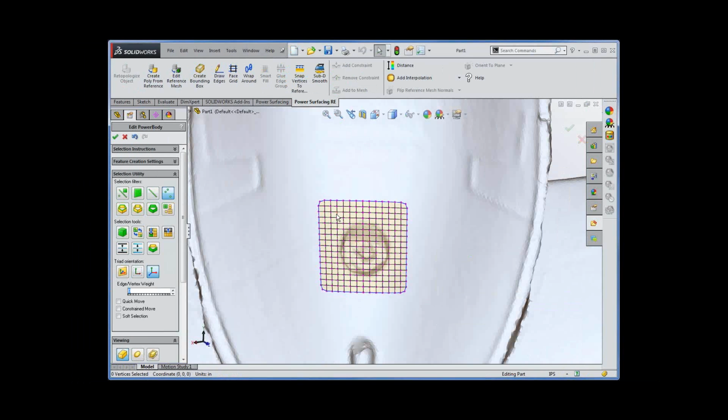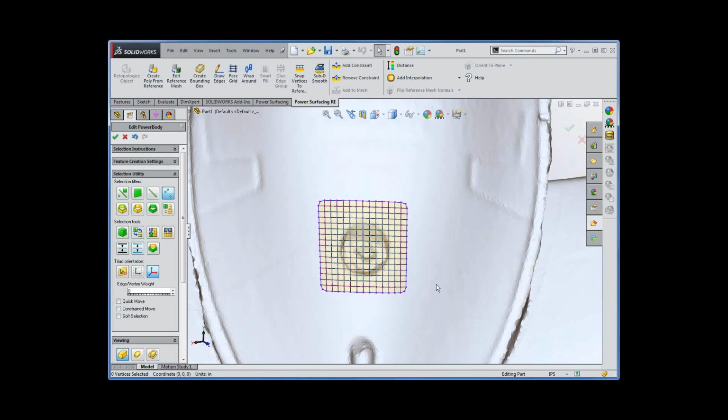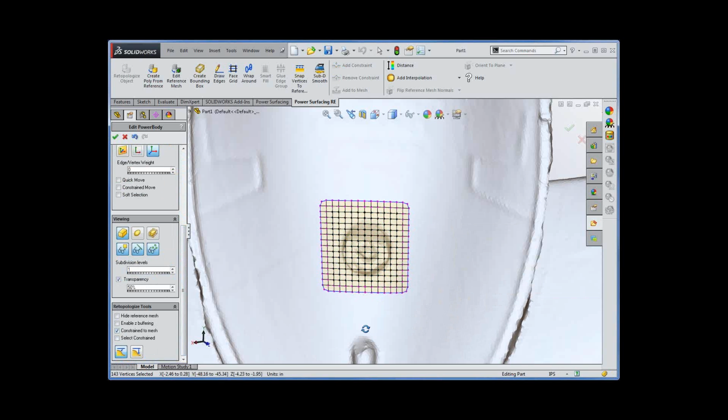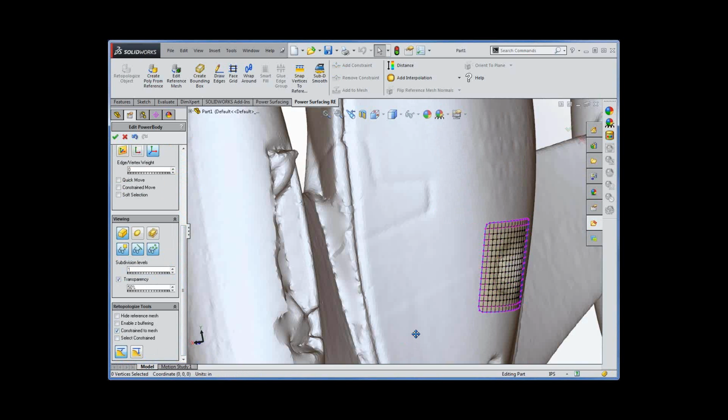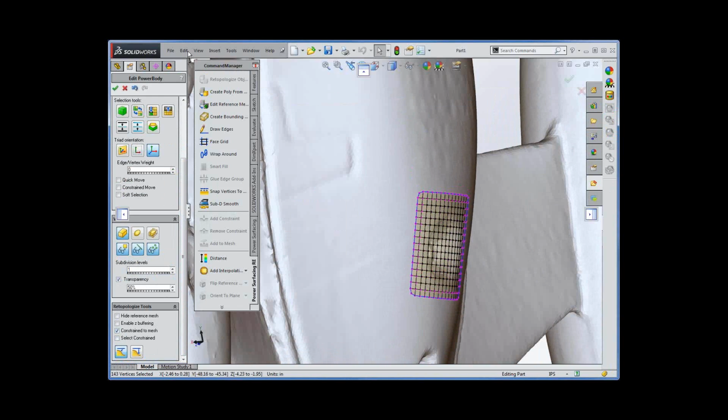And then I'm going to select inner section, and I'm going to set these vertices to unconstrained. I click that, here in my right-click menu. So I unconstrain them. And if I click outside here, you'll see now that they're black. So remember, magenta is constrained to the reference mesh. Black is not. Now it's safe to go down and turn on constrain to mesh again. And we won't see anything happen until it updates. And we do that. Oops. Oh, this is not good.